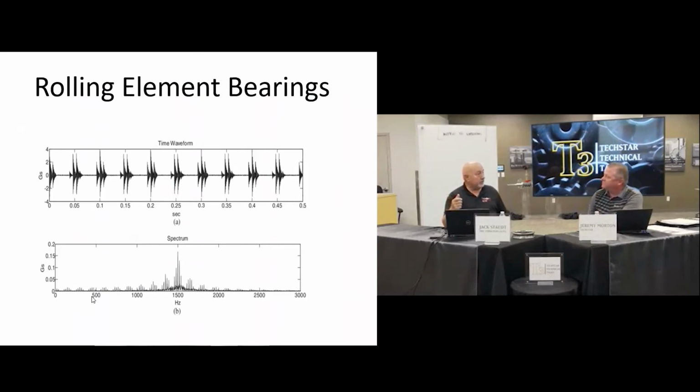If you're in stage 1, we always recommend maybe lubricate it a little bit and keep on monitoring. We get to stage 2, we look at it and say, it's still not ready to change out, but keep on monitoring it. When you get to stage 3, we tell our customers we need to start planning. We know from case histories that a bearing at this speed will probably last 60 to 90 days. So we have some type of number to work off of. How long do we have? And then we get to stage 4, we're rolling the dice. We don't know when it's going to fail, but it's going to fail. Running on borrowed time. That's right.